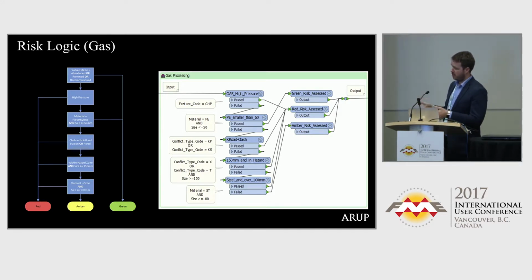and the K road. So it was a cut and cover structure for the project, and we also had another zone in addition to our track slab zone, which we call the kinetic envelope. So when you've got your tram, you can't have anyone within a certain zone. And if we had a manhole that ended within that zone, that would automatically be a failure as well. But we also had, as part of this logic, if the start or the end node was within the kinetic envelope, that would actually be a divert automatically for the asset that went between the two nodes.